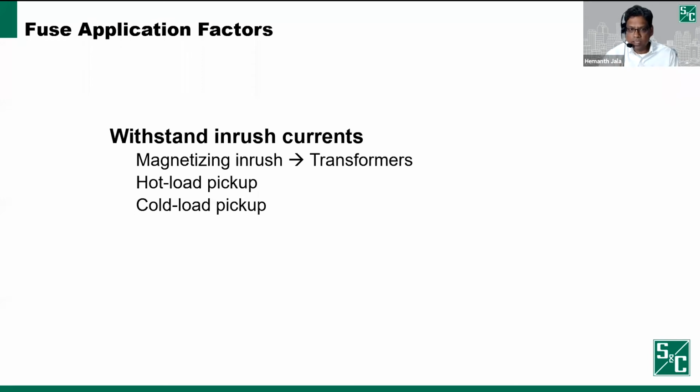When it comes to transformers, the important thing is that you want to make sure a fuse can handle the magnetizing inrush of the transformer. And we'll take a look at that when we use an example and see how picking a fuse works and how it can handle the magnetizing inrush of a particular transformer.